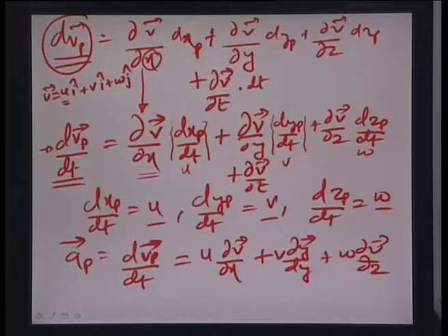So, v with respect to x has already been independent of t. So, it is a constant as far as differentiation with respect to t is concerned, and this right here is the new term which comes out, and xp can of course be differentiated with respect to t, and this gives the instantaneous velocity of the particle in the x direction at the point p. Okay. So, that is how this equation of acceleration emerges from the previous equation.